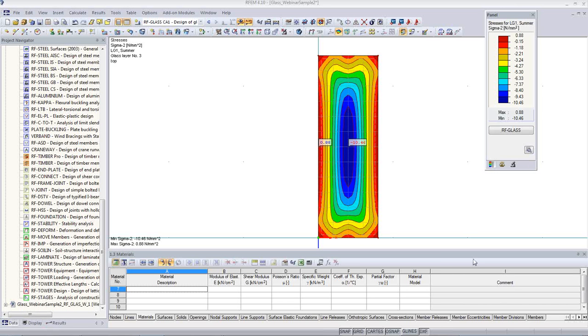How can the argon gas transfer pressure load from the external glass surface to the internal one? Well, you have to imagine that there is an enclosed gas with a certain volume, and if you compress it, this system will have an effect on the other surfaces that are boundaries for that volume.